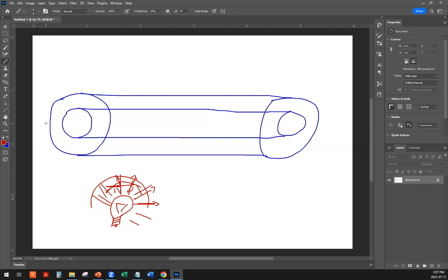So here is the little bit of a problem. Let's say one of the modes is going to be light going straight through it. Now let's say there's another mode that enters the core at a different angle. So it's going to keep bouncing off the interface between the core and the cladding. And let's say here, at the same time, these two are going to get to the end, and the longer the cable is, the bigger the difference is going to be.